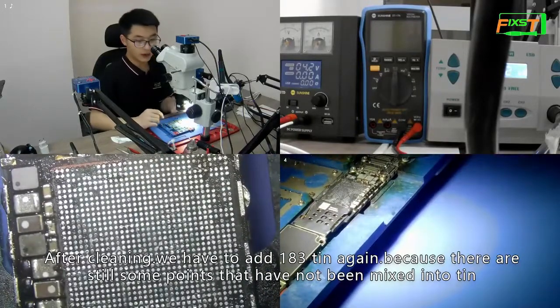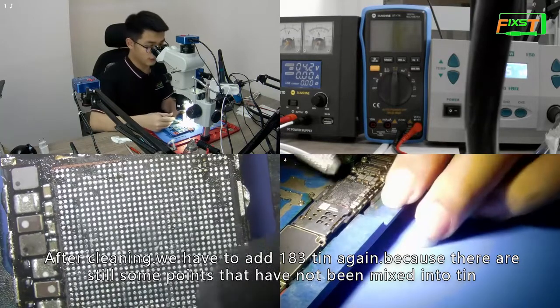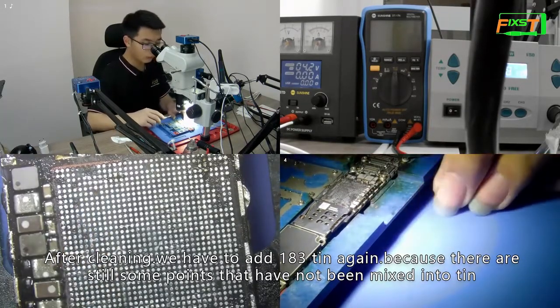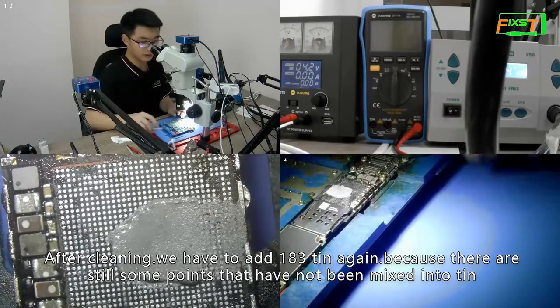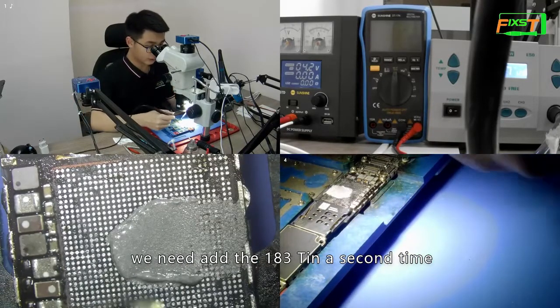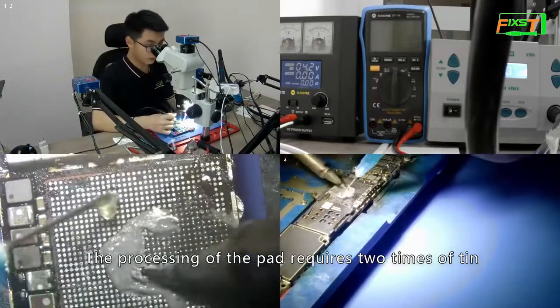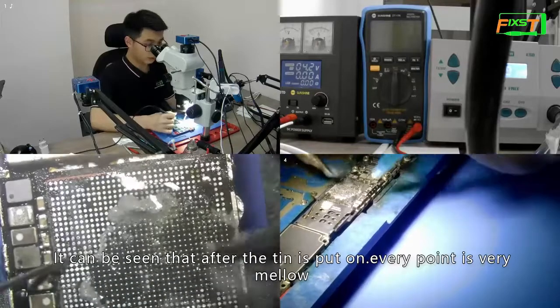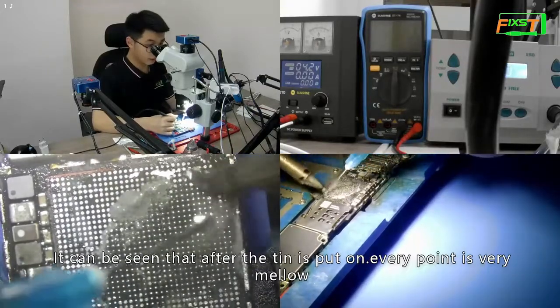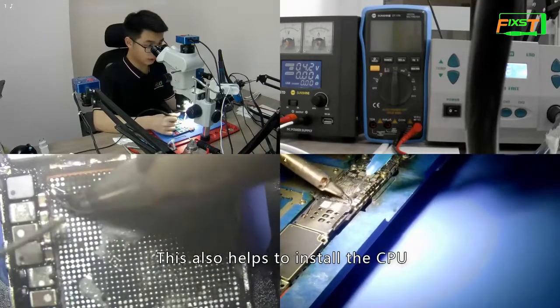After cleaning, we have to add 183 tin again, because there are still some points that have not been mixed into tin. We need to add the 183 tin a second time. The processing of the pad requires 2 rounds of tin. It can be seen that after the tin is put on, every point is very mellow. This also helps to install the CPU.